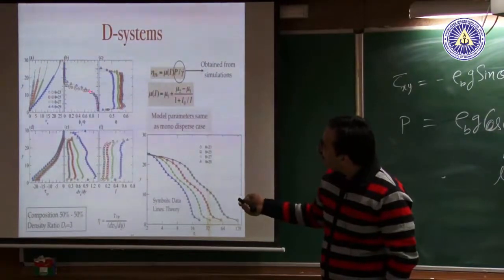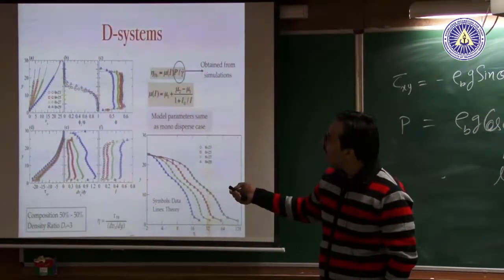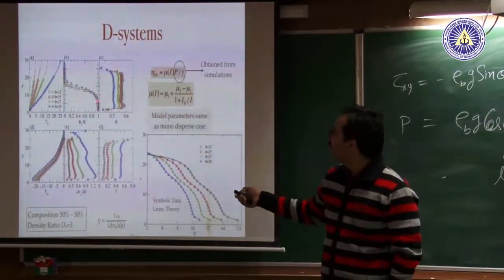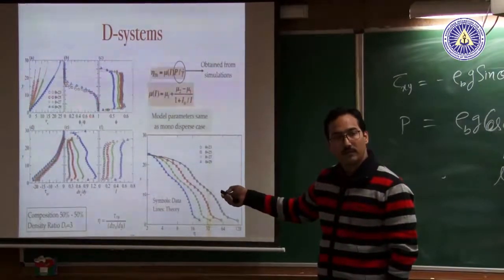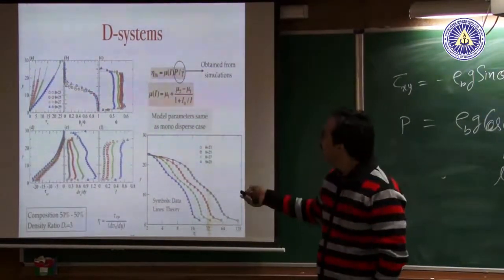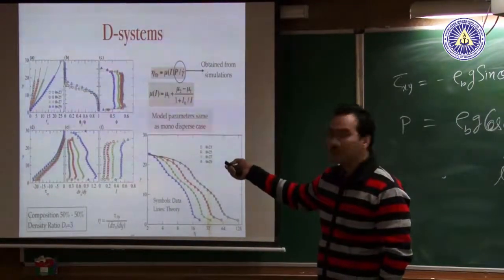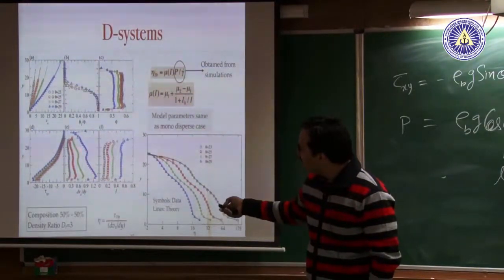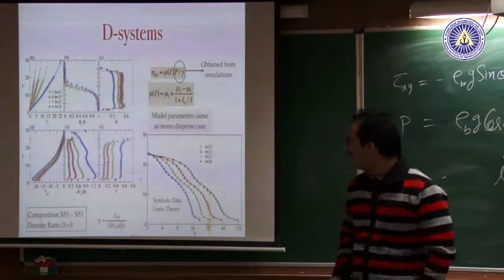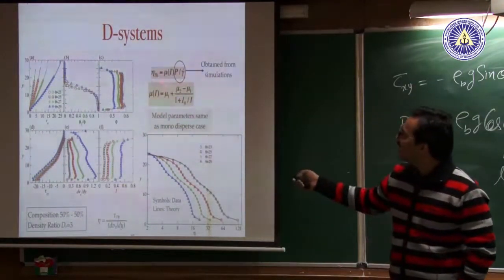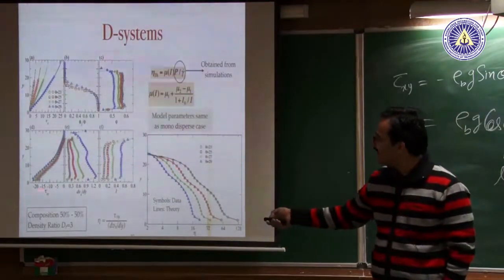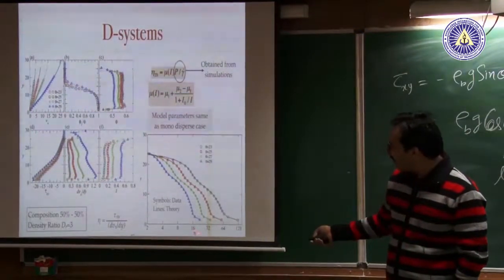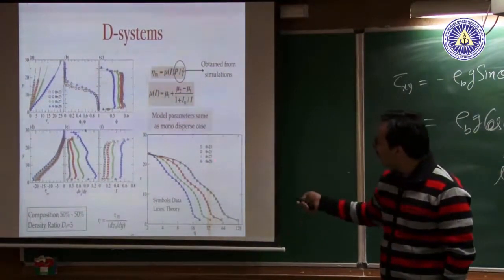This is the packing fraction concentration variation. Concentration of the heavy particle is 0 at the top, meaning no heavy particle here, and all heavy particles are concentrated in the base, so it's a very highly segregated situation. The packing fraction though shows very little variation, more or less constant in the bulk. Your shear rate shows sort of two regions, two linear regions with some connection in between, but if I try predicting the viscosity, I can measure the shear stress and shear rate from the simulations, and I plot the effective viscosity along with height for different theta.